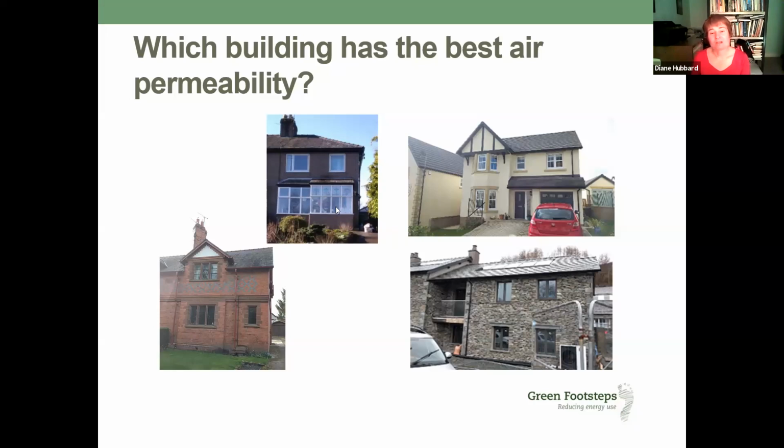So quite a long while ago now, I did some research. I did lots and lots of tests on existing buildings, and what people told me before I started that research was there'd been very few tests done on existing buildings. And what people told me was that they were expecting older properties to be roughly twice as leaky as new properties. So air permeability wise, of the order of 20 was what people were telling me, but nobody had actually gone out there and tested properties.